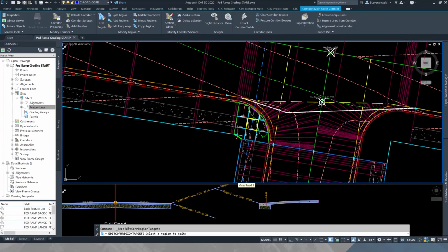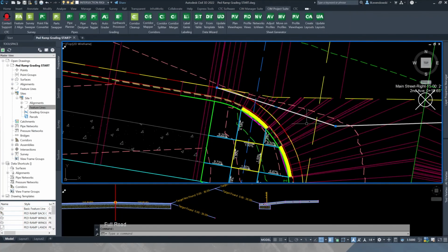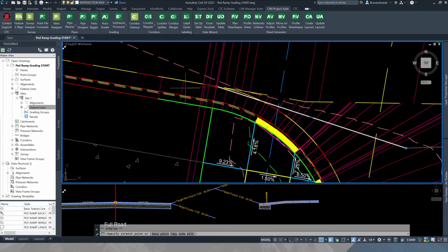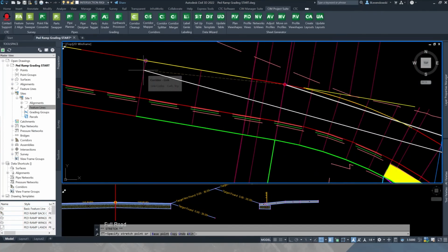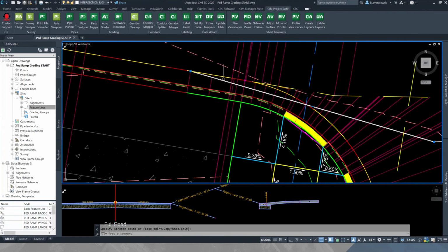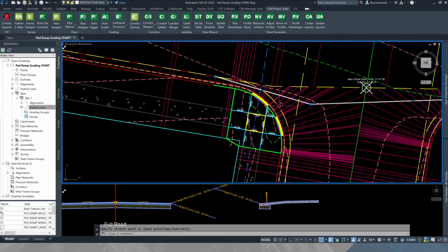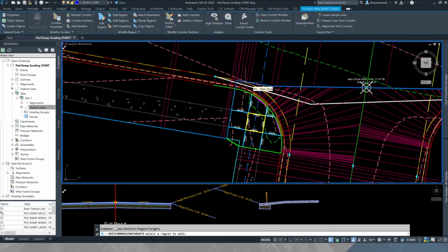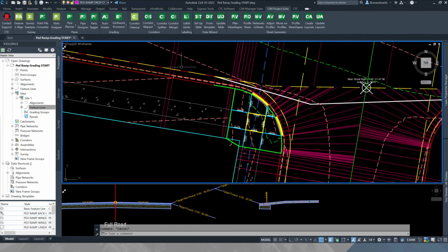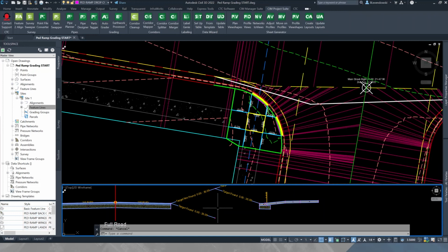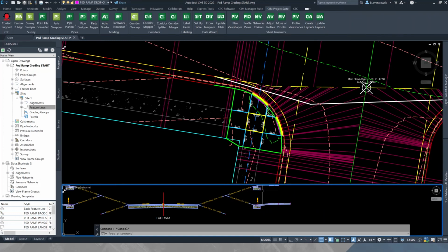Okay, and I'm just using a kind of an empty conditional to have it turn off the curbs through that intersection. Now I use a simple polyline for that conditional, so what we can do is take this and say, we need to extend the curb ramp region further back. That means that this region right here is going to extend further back now. And it also means that it's going to not build any curb or sidewalks or anything further back.